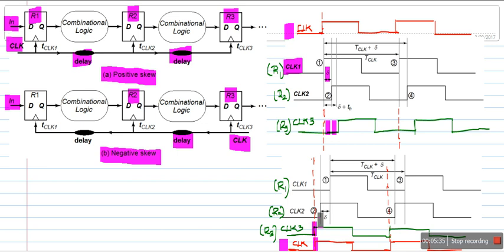You see the phase shift between the main clock and clock 2 is a phase shift of delta, and that delta is represented by this area. In the case of register R1, it receives the clock signal after a delay of twice delta, so this delay is these two delays, between clock 1 and clock 2.